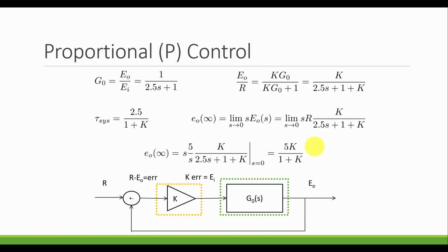So in general, analytically, before we get to simulation, the higher the value of K we choose, the faster the system will respond because our time constant will get smaller. And the higher K we choose, our steady state voltage is going to approach 5 volts, but not reach it. So a downside of this controller right now is we're not going to get exactly the output at steady state that we want. However, with higher gains, it will at least respond faster.